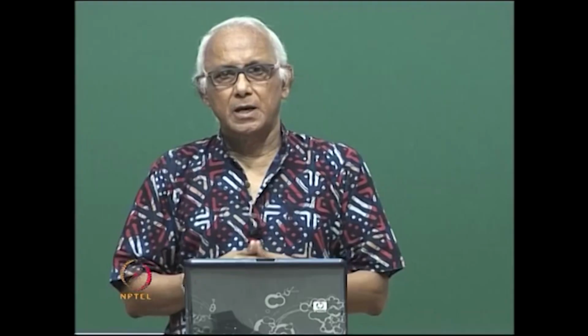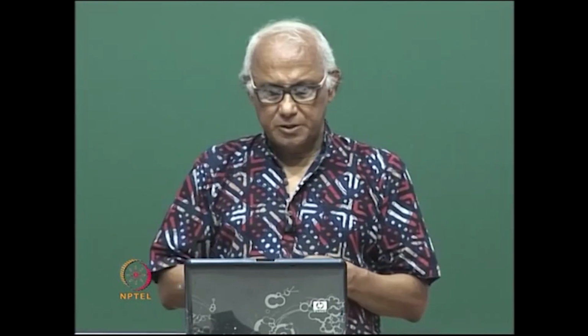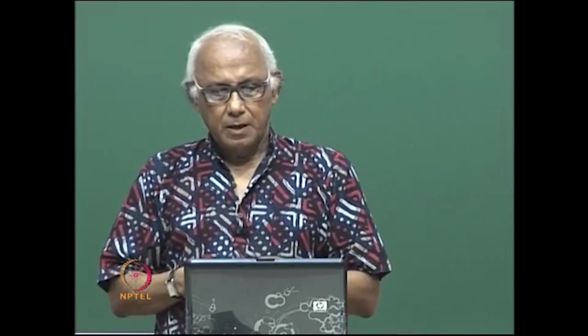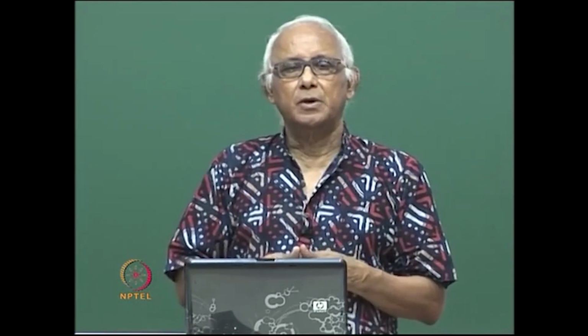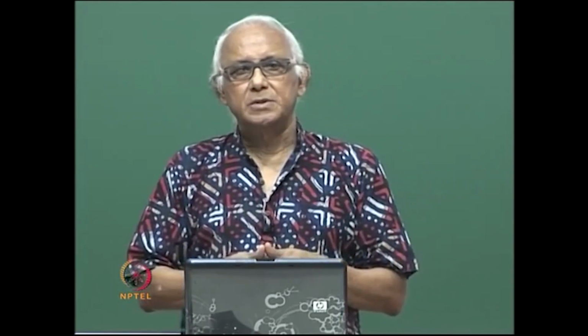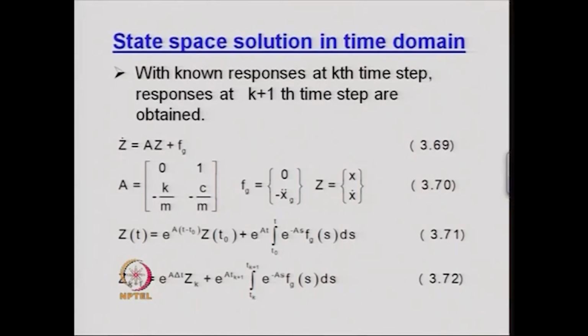In the previous class, we discussed the time domain analysis of structures for specified ground motion, and in that we described two numerical integration schemes. One is the Duhamel integral, the other is the Newmark-Beta method.